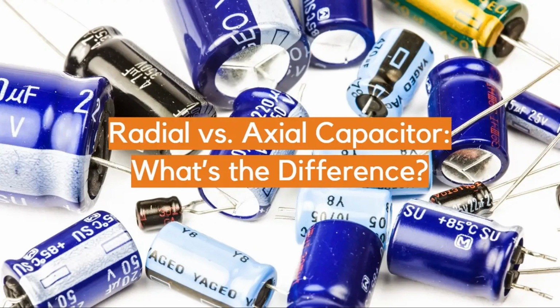Tantalum electrolytic capacitors. Tantalum capacitors generally offer better capacitance stability compared to aluminum electrolytic capacitors. They have lower temperature coefficients of capacitance, which means their capacitance is less affected by temperature variations. Tantalum capacitors also exhibit less capacitance change with voltage compared to aluminum capacitors.